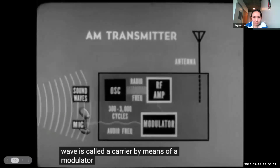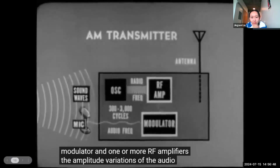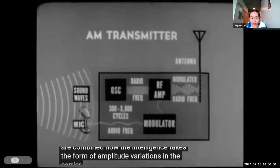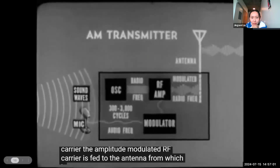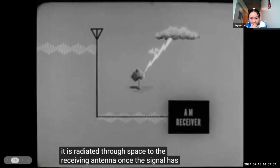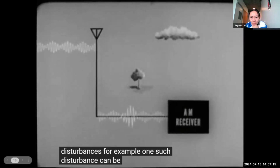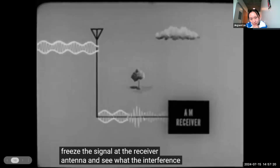By means of a modulator and one or more RF amplifiers, the amplitude variations of the audio signal and the radio frequency carrier are combined. Now the intelligence takes the form of amplitude variations in the carrier. The amplitude modulated RF carrier is fed to the antenna, from which it is radiated through space to the receiving antenna. Once the signal has left the antenna, however, it can be affected by many disturbances. For example, one such disturbance can be lightning. Let's freeze the signal at the receiver antenna and see what the interference has done to it.